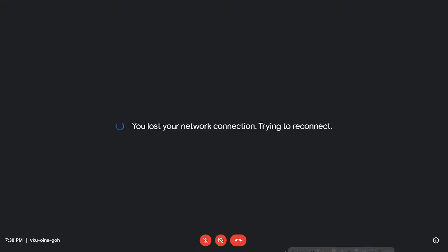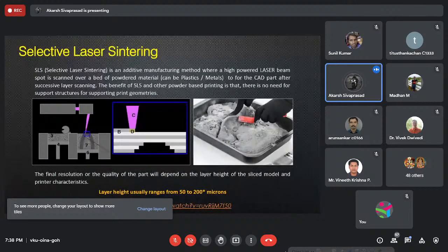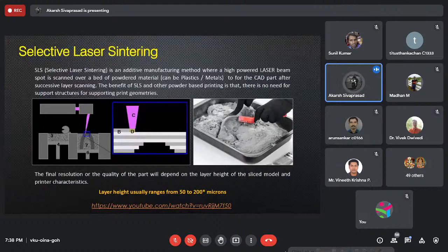And so this, I would say, the material is really hard. Since it's porous, there are some materials which need to be sintered. So whatever you get out of the printer is the green part. You have to put it in a sintering oven if it's a metal to completely cure it, or if it's a nylon-like plastic, then you have to dip it into some kind of a percolant to seal all its pores, and then make it more hard. So it's more hard, again more brittle because of that,